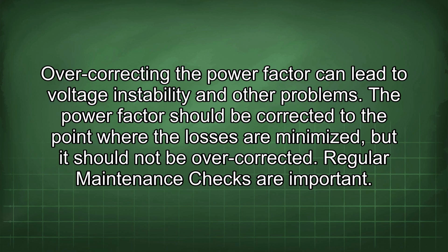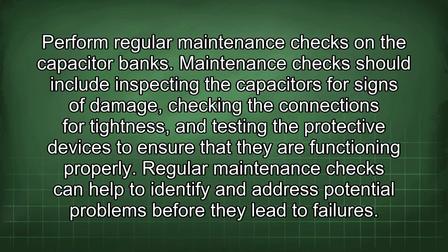Regular maintenance checks are important. Perform regular maintenance checks on the capacitor banks. Maintenance checks should include inspecting the capacitors for signs of damage, checking the connections for tightness, and testing the protective devices to ensure that they are functioning properly. Regular maintenance checks can help to identify and address potential problems before they lead to failures.